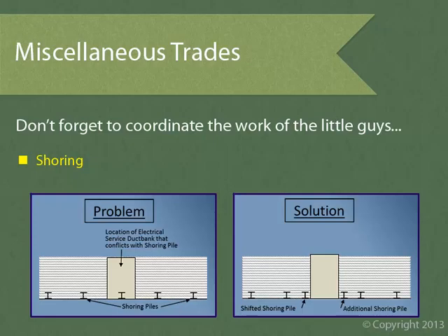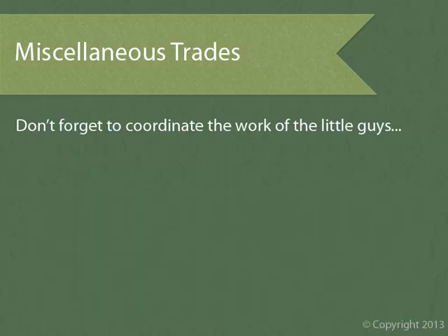Shoring is a temporary structure, typically done by the design-build contractor, and is considered a means and methods of construction, so it's the general contractor's responsibility to coordinate the work with the other trades. Now, the vast majority of exterior skin coordination work won't even begin until facade submittals start rolling in, but be sure to coordinate the below-grade waterproofing system immediately after the notice to proceed is issued and in conjunction with the shoring, rebar, formwork, and concrete submittals.